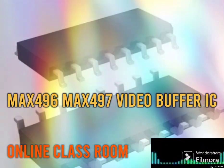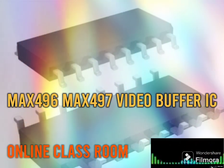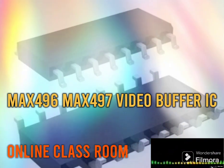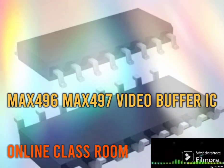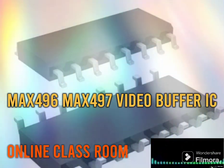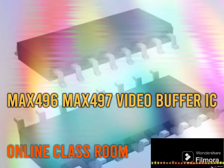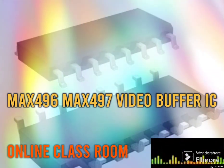The max496 and max497 have lower total noise compared to other current mode feedback amplifiers, which typically have higher input current noise. The dominant noise source in current mode feedback amplifiers is the input current noise multiplied by the feedback resistor. In video applications such as NTSC, PAL and SECAM, differential gain and phase error are important specifications as they directly affect color changes. The max496 and max497 have ultra-low differential gain and phase errors, making them ideal for broadcast quality composite video applications.